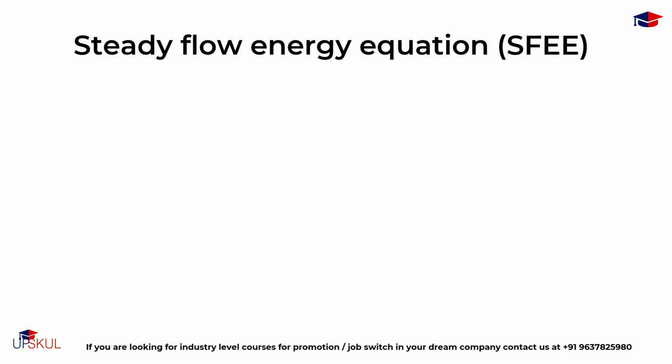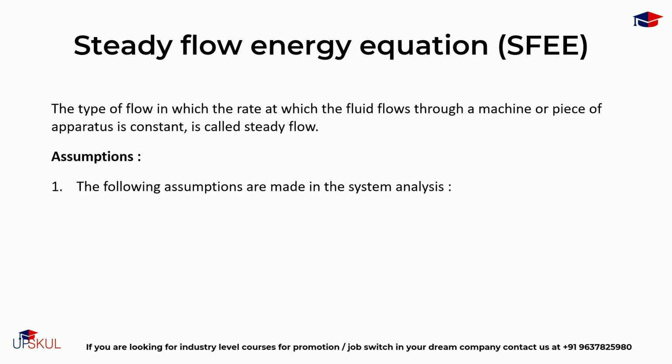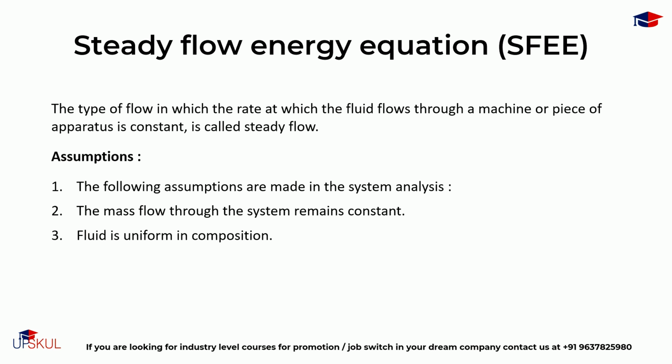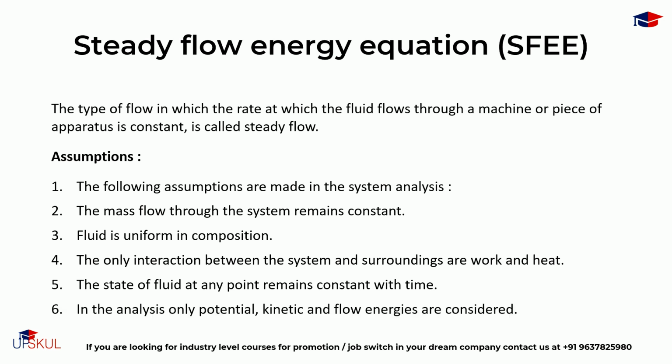There are some assumptions that are made in system analysis during steady flow. First, the mass flow through the system remains constant. Fluid is uniform. The only interactions between system and surroundings are work and heat. The state of fluid at any point remains constant with time. And in the analysis, only potential, kinetic and flow energies are considered.